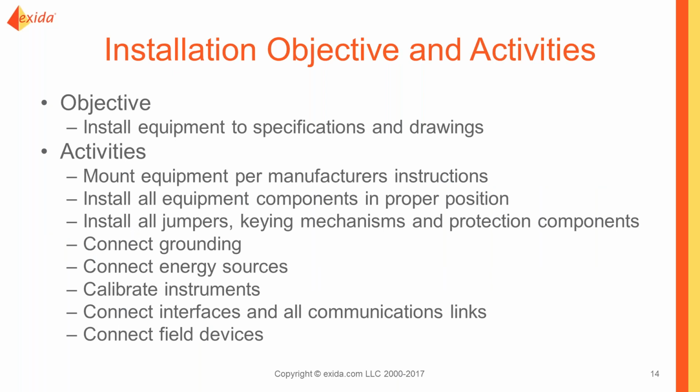When we look at the different typical steps that you'll find in a process plan that come before the functional safety assessment, we'll look at installation, commissioning, and then some validation steps. Mostly today, I'm going to focus around functional safety assessment 3. So IEC 61511 points out 5 different points where a functional safety assessment could be conducted. The first is after the SRS is written. The second is after conceptual design, after design. And often that's tied in at the FAT.